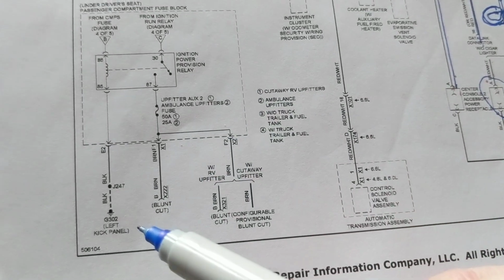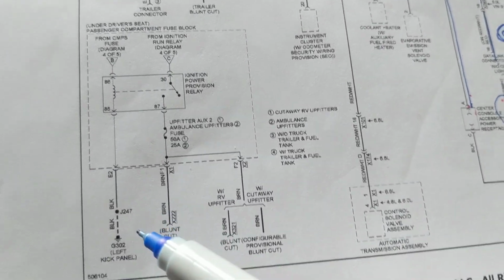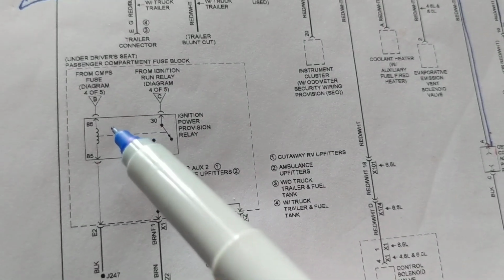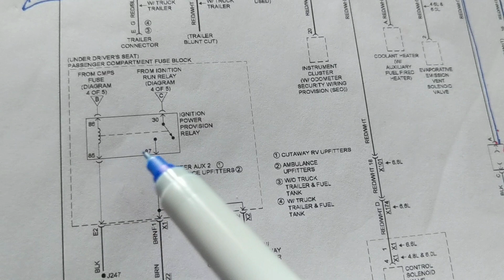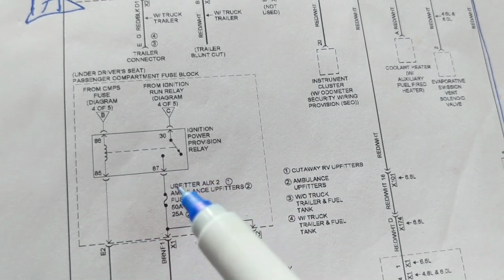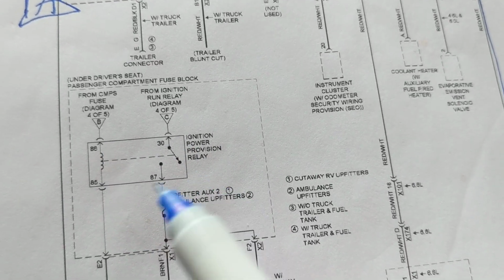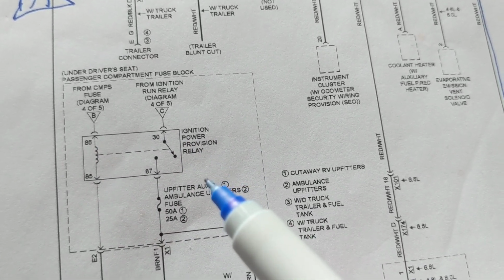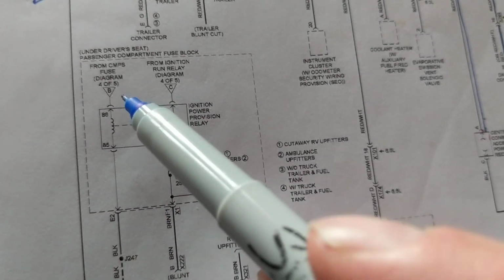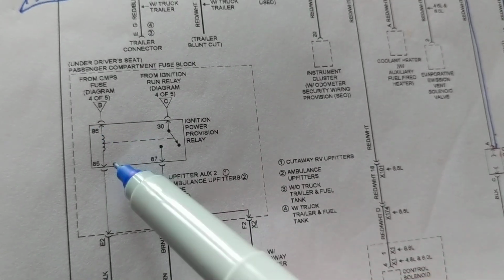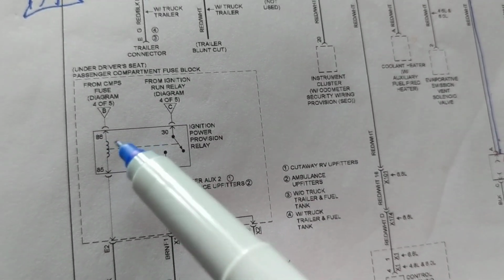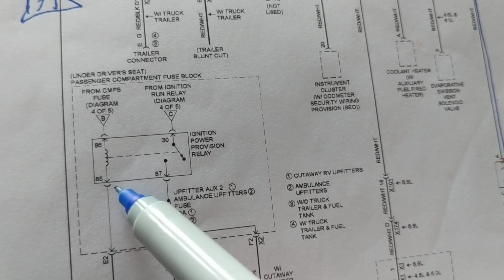As I specified before in the videos, two things have to happen for a relay. And relays are used for fuel pumps, for the lights, for everything. Once you understand one, you'll understand all of them. Two points have to be connected to this coil. This is a coil that gets magnetized as current flows through it.